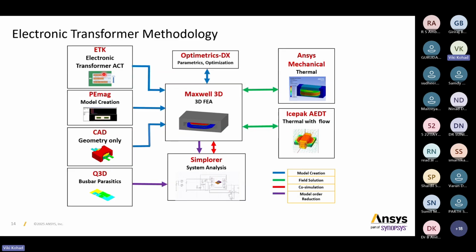So you have to just give the parameters, like which type of core you have. Like if you have an E type core, you have to select the core type, you have to select the supplier type, and you just need to give the dimension parameters. Then you have to select the winding layers, how many layers you have, and whether they are combined in series or parallel electrically.